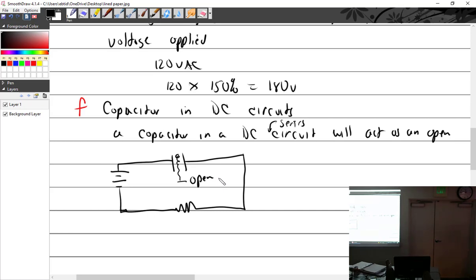If I discharge it, now it's discharging. So it's stored up electricity, and then I discharge it out. And I go back on, it's got nothing. But it's in series, so we'll have it flow. How long will it flow? Five time constants. How did you know I was going to say that? All right, and we discharge it, and that just takes it back the other way.